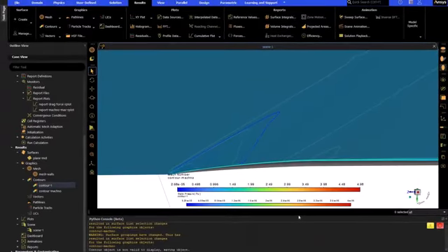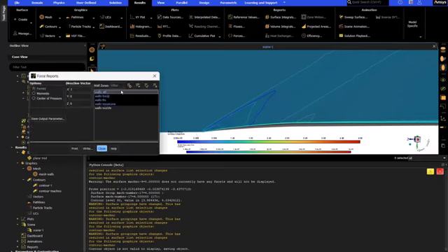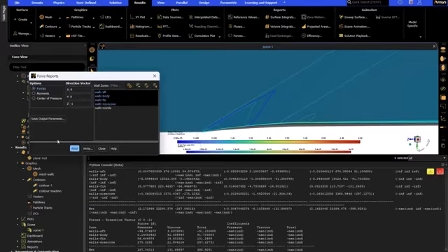The calculated value for drag of the rocket can be found in the force reports under the Results tab. Selecting all the exterior walls and aligning the direction vector with the flow prints the results for the pressure drag, viscous drag, and total drag for each part of the rocket, which gives the total drag force. However, the drag coefficient values are not real numbers.